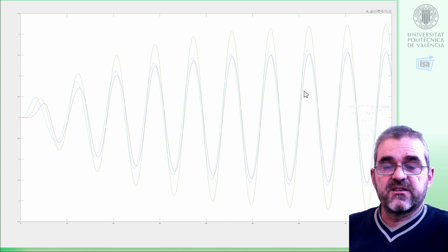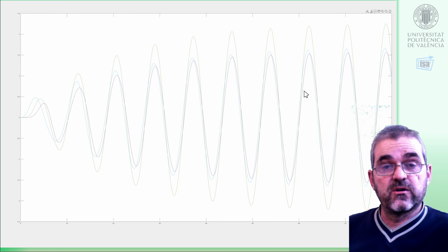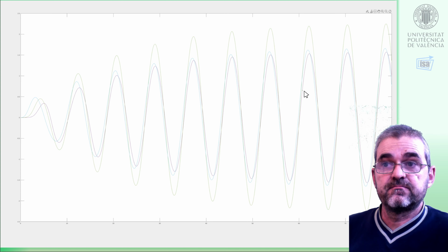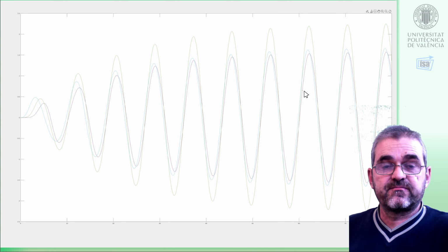In here, we are just discussing, so we'll summarize and conclude. In this video, we are just discussing how to encode the linear system of equations. It's easy, just copying A, B, C, D. And once we define initial conditions and input, we can solve it with a generic solver, such as ode45, or we can simulate the time response with a specialized solver for linear systems, such as lsim. We did both ways here to compare, but of course, in a real setup, I would use ode45 if my system is nonlinear, and lsim if my system is linear.